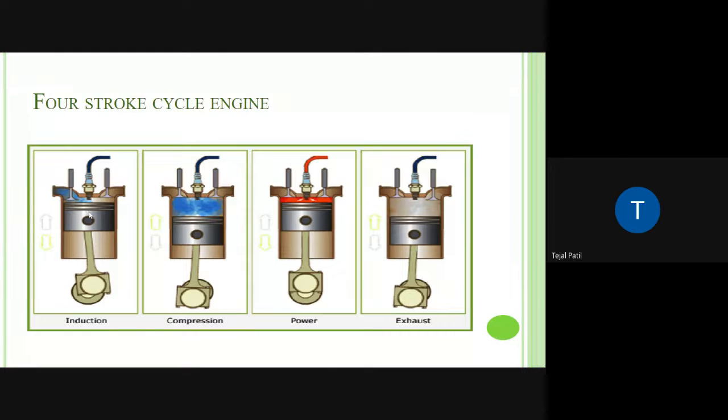Now, the initial motion has been given already, but after that, are you kicking it again and again? No. Then how is the piston going to move? The piston is basically moving because of the combustion process over here. For that, let's understand from here. When you have given the motion, the piston will start moving up and down. Initially it is at the top level, and above this piston there is nothing, only air, and that air is also a very small volume.